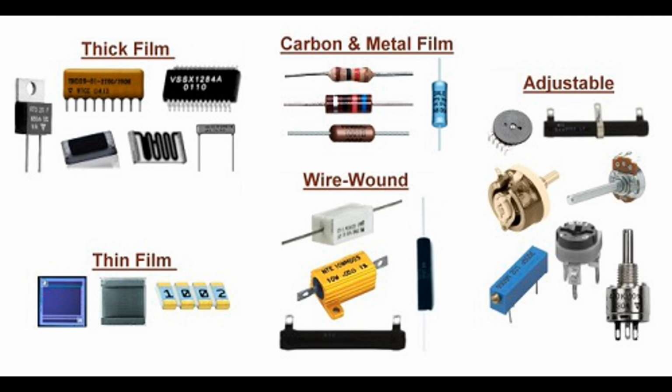Resistive matching. Description: using resistors to adjust the impedance of the source or load. Example: in audio circuits, resistive attenuators, pads, are used to match impedance between different audio components, ensuring consistent signal levels. Transformer matching. Description: transformers can match impedance by adjusting the voltage and current levels.